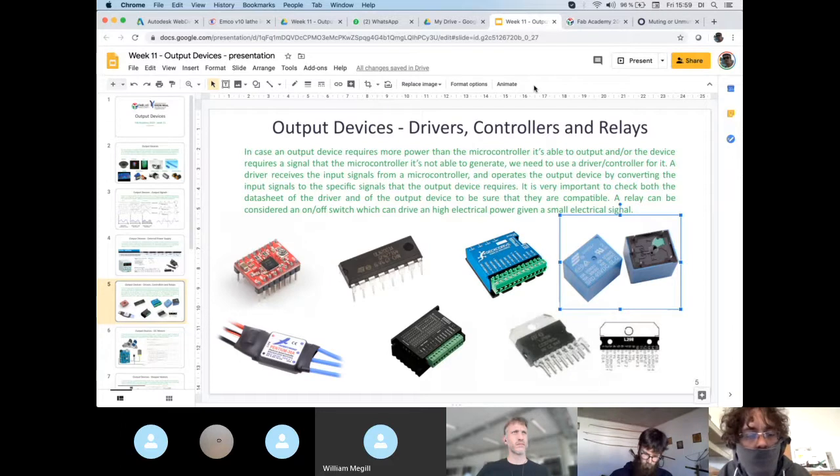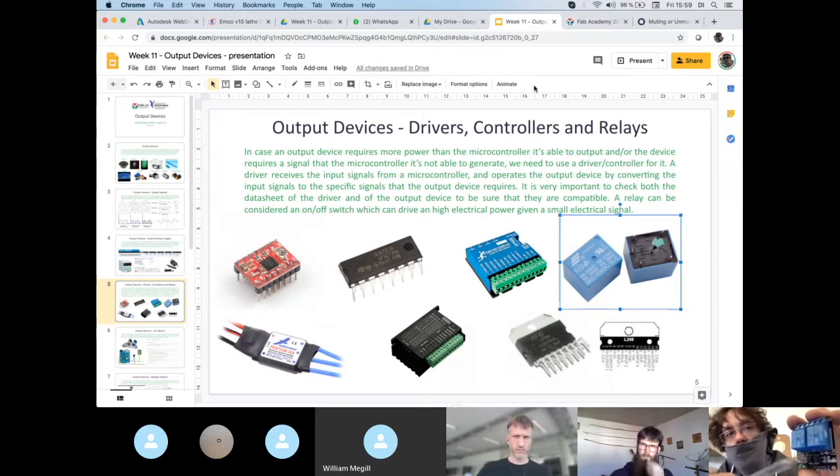Sometimes you also have additional security things, like diodes here, opto-isolators over here, and so on, depending on the kind of relay. If the isolation inside the relay is not so good, you can also use opto-isolators.